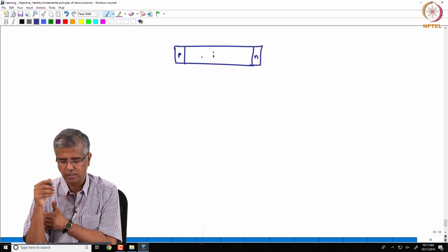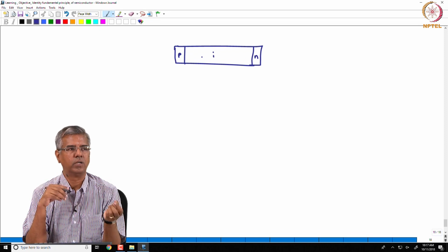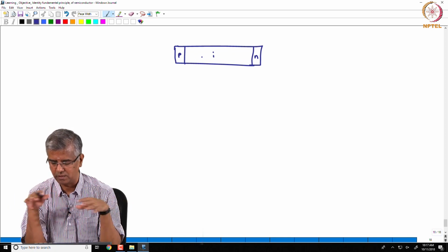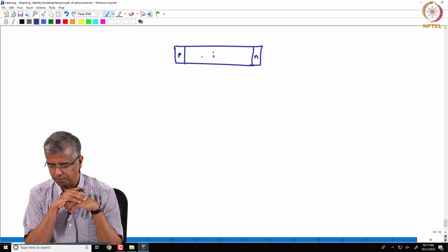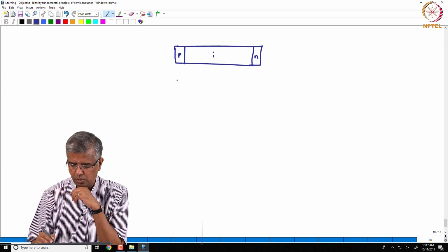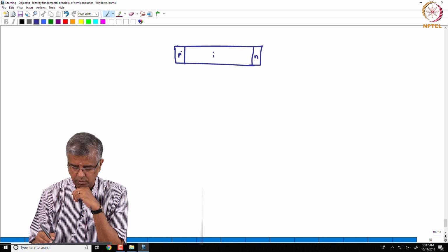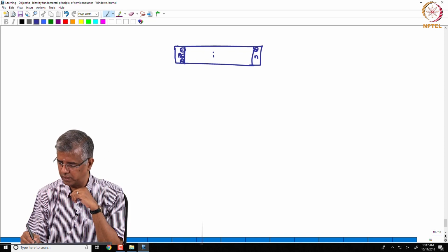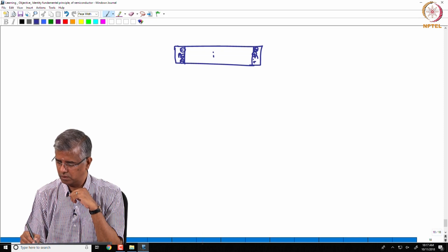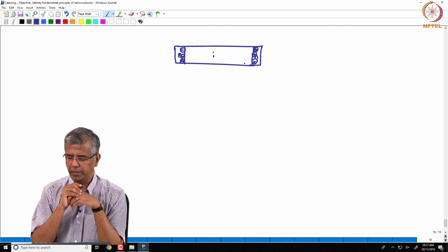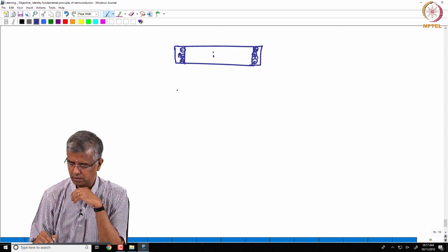So, the electron and hole concentrations are essentially the same in an intrinsic semiconductor, and the Fermi energy is right in the middle of that band gap, right. So in this case, when you look at the charges that are present, the charge density is going to be such that you have negative fixed charges over here, positive charges over here, okay.